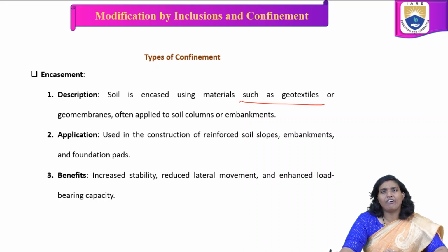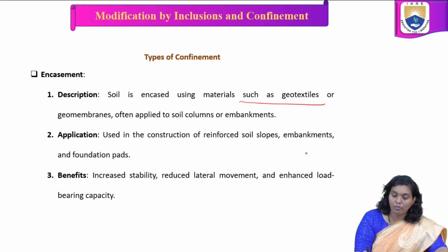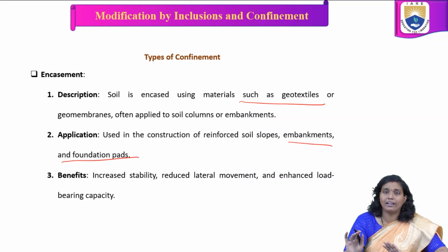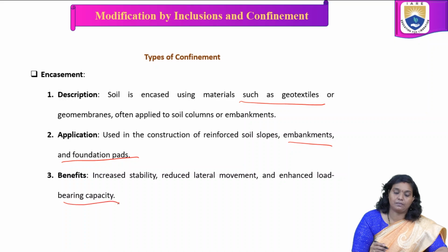In this type of confinement, we are going to use it in the construction of reinforced soil slopes, embankments and foundation pads. Using this type of confinement leads to increased stability, reduced lateral movement and enhanced load bearing capacity.